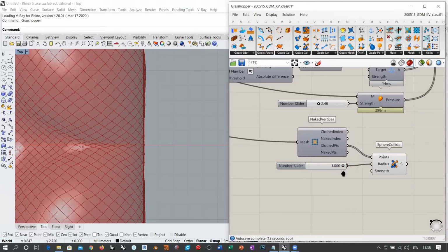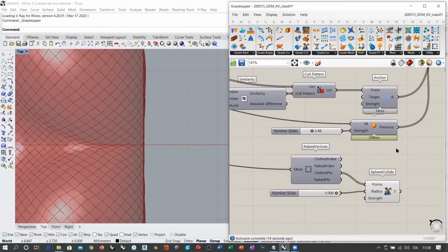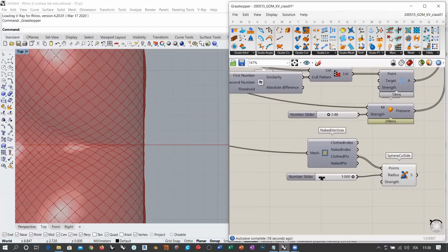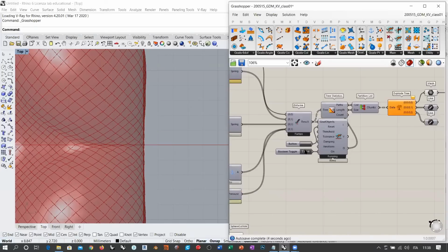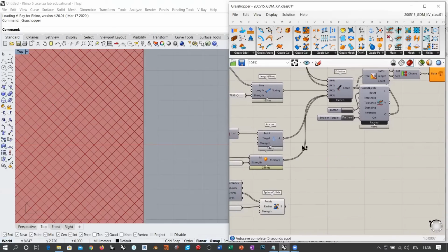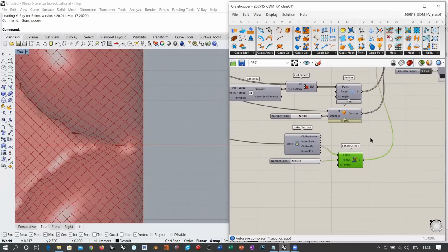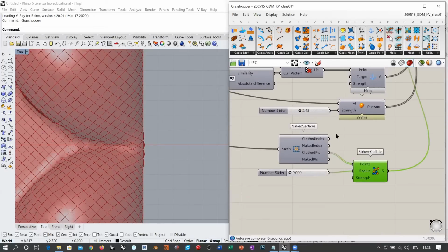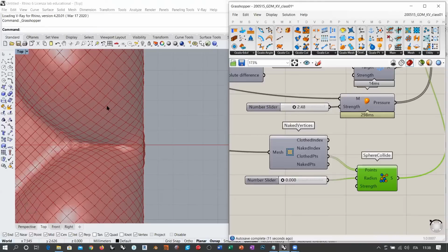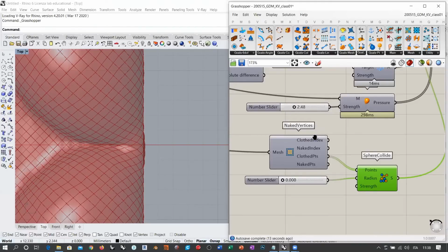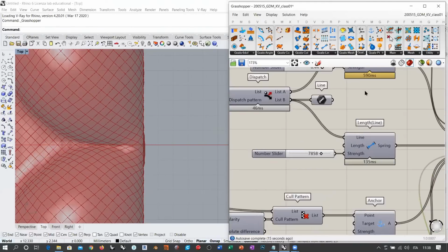Remember that when you work with the pressure, things are more delicate than the usual. So I'm going to decrease this initially to 0, and stop the simulation, reset the simulation, and apply this to the non-geometrical goals. Okay, so what happens now that we are working with pressure? Pressure tends to expand the mesh, and it's only balanced actually by the elastic properties.